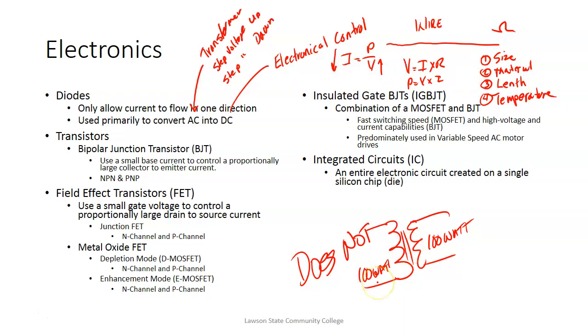So if this is a step-down transformer, which means if I got 100 volts over here and 50 volts over there, if I've got 1 milliamp over here, then I'm going to have 2 milliamps over here. So when we say a transformer steps up and steps down, if we step the voltage down in the transformer, the current's got to go up on the low side